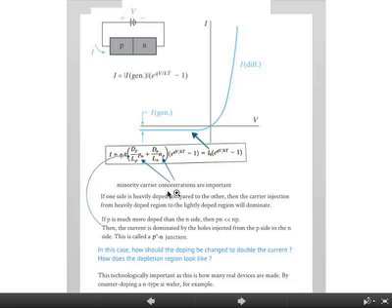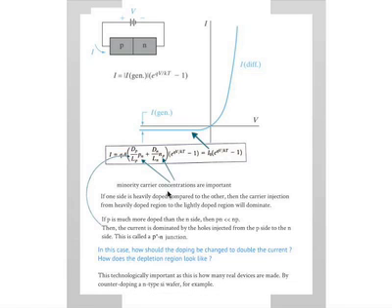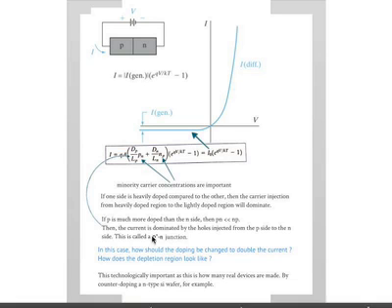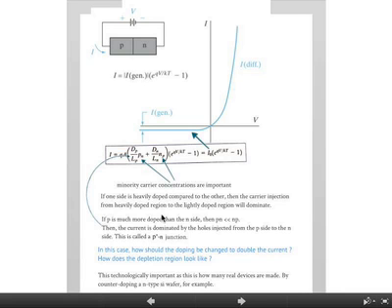And this is practically important because in most devices that are actually made, one side is very heavily doped, and the reasons for this you will understand later in the class. But it's very common that you have a P plus N junction or an N plus P junction, and so on. If P is much more doped than the N side, then Pn is much smaller than Np, then the current is dominated by the holes injected from the P side to the N side. And this is called the P plus N junction.